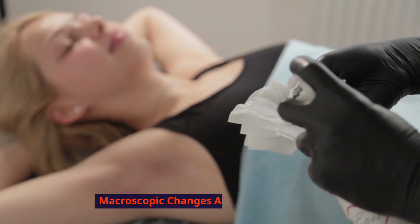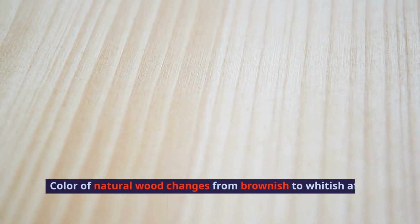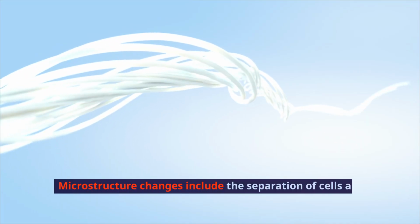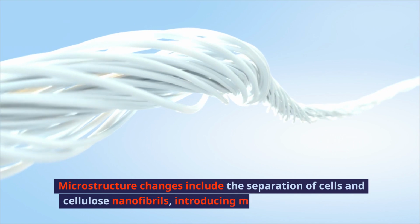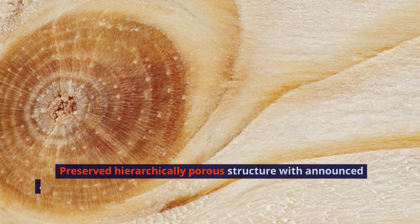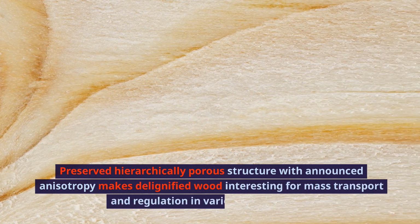Macroscopic changes after delignification. Color of natural wood changes from brownish to whitish after delignification. Microstructure changes include the separation of cells and cellulose nanofibrils, introducing massive nanochannels. Preserved hierarchically porous structure with pronounced anisotropy makes delignified wood interesting for mass transport and regulation in various applications.